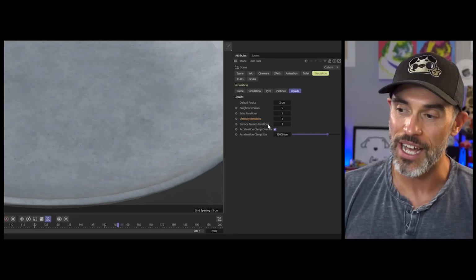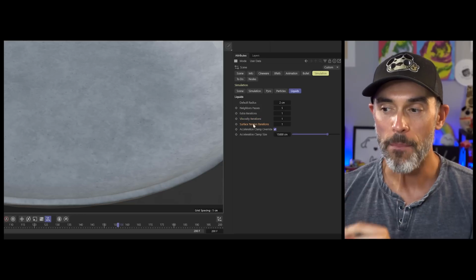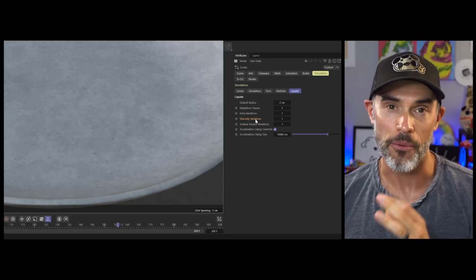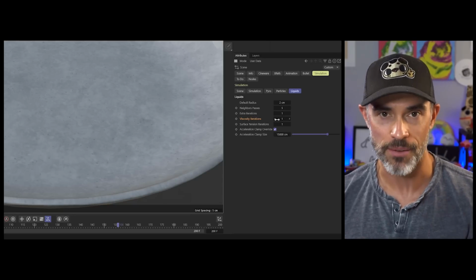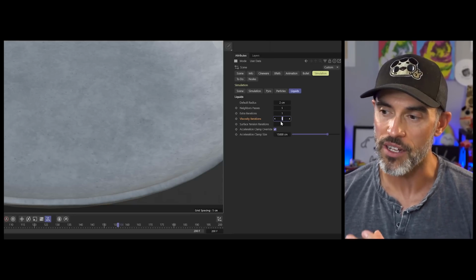And so what I've been told by Noseman at Maxon, he's really given me a lot of information about this stuff. What he told me is that what you want to do is up these viscosity iterations so you have the best quality of these features, and then go in and dial in the strength of them. Because the one other gotcha in Cinema 4D is, if you're familiar with using the sub-steps in cloth, once you up the sub-steps or the accuracy of the simulation, one of the byproducts is that it makes the simulation stiffer.